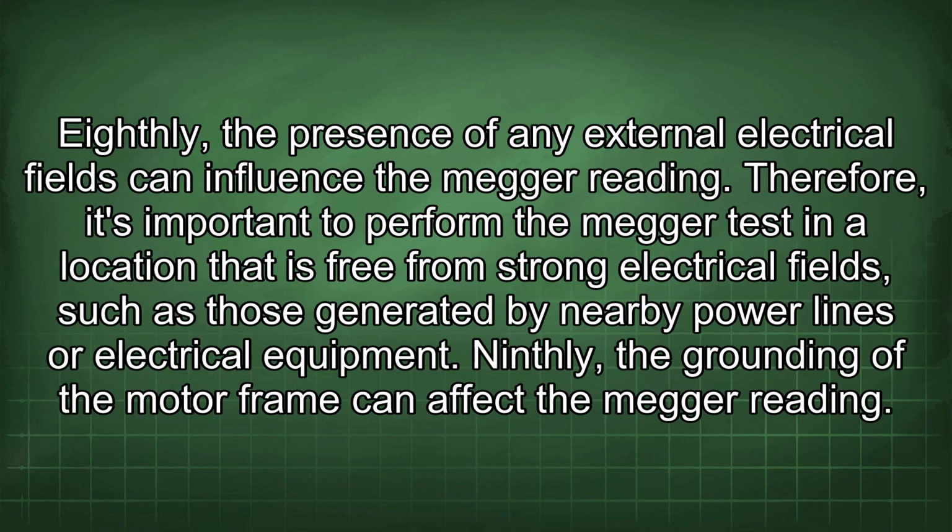Eighthly, the presence of any external electrical fields can influence the Megger reading. Therefore, it's important to perform the Megger test in a location that is free from strong electrical fields, such as those generated by nearby power lines or electrical equipment.